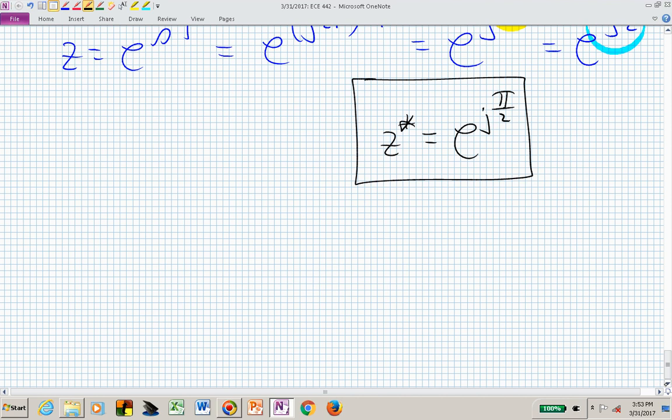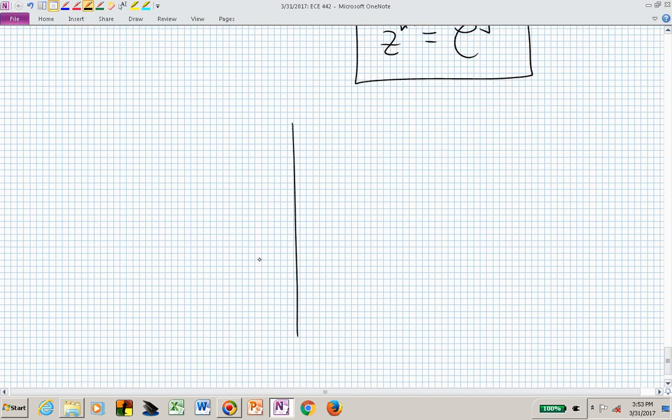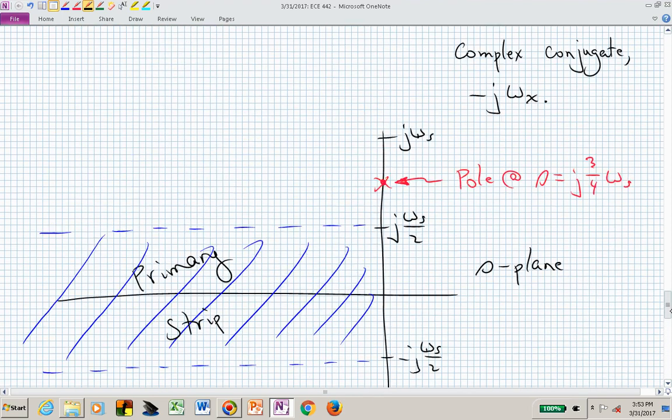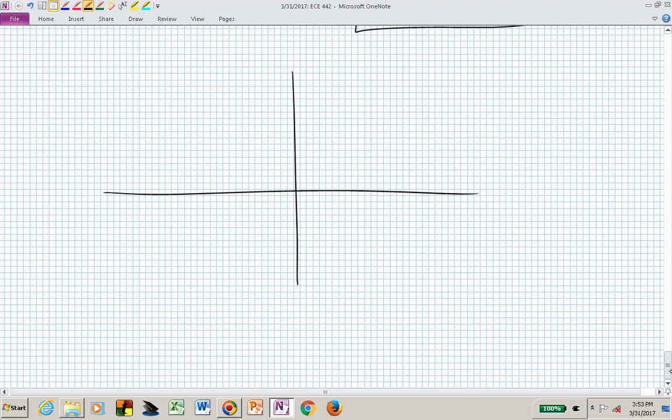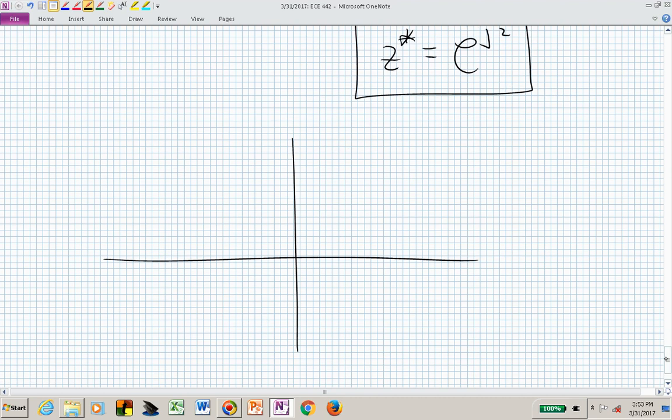Or, in the z-plane, what we have is, in looking at a frequency that's beyond our Nyquist frequency, here we're saying, let's say that this is now at 3/4 omega sub s, we now are showing in the z-plane that we've not only transitioned around 180, but we've now gone all the way down to 270.